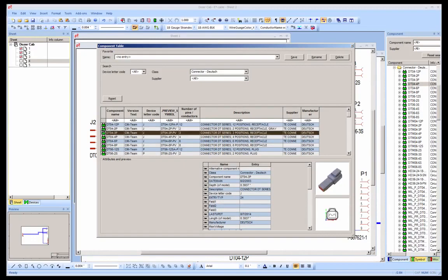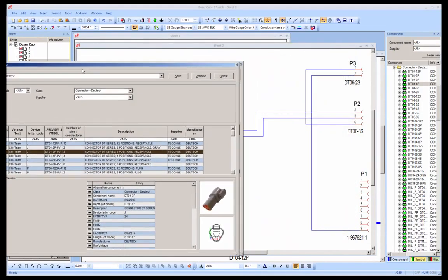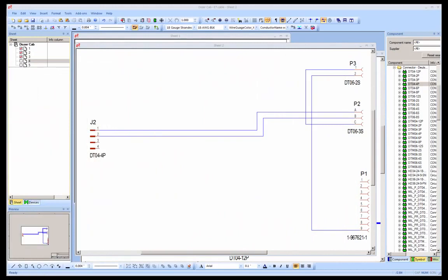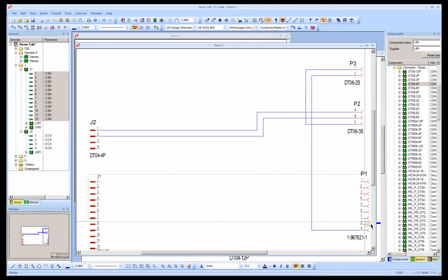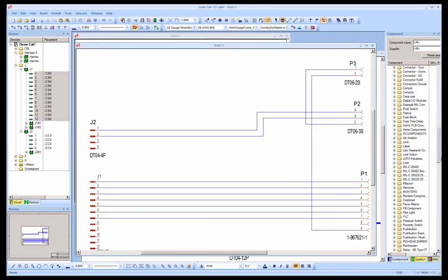As this project is nearly complete, we will add a connector to the existing diagram, add the connections, and assign wires to those connections. The 12 pins of connector J1 are added to the sheet, and 7 of those pins are going to be connected to J2. At this point, wires can be added to the connections.